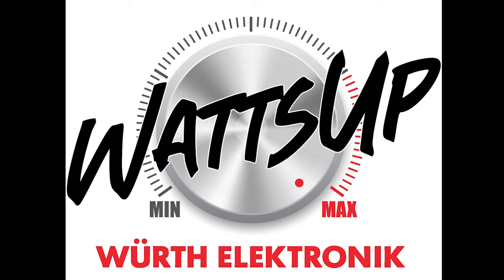And this brings us to our fourth design tip: DC resistance with the same size. For higher inductance, you get higher DC resistance. Lower inductance gets lower DC resistance. And the same inductances for a shielded inductor get lower DC resistance. The DC resistance is essential in determining the wire heating losses, and this is another important parameter for minimizing the power loss of the power inductor.